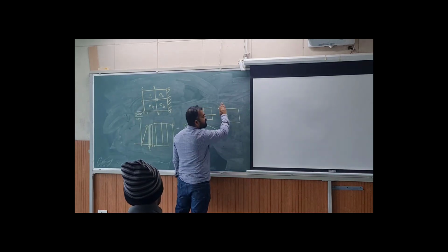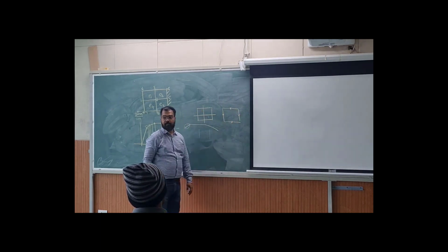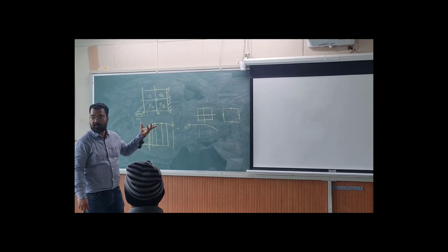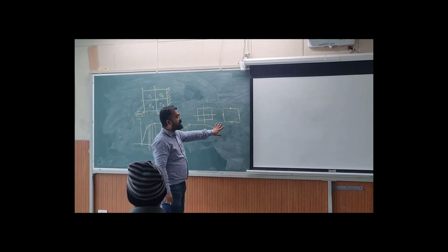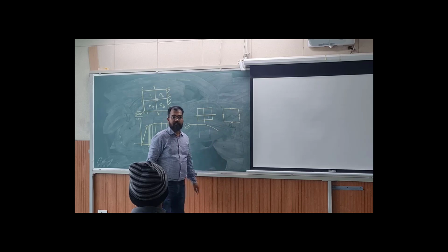So I make it a quadratic shape function, which will mean that there are mid nodes. So again you will have, well, a smaller number of degrees of freedom. A little bit less in comparison to that one. So here you have 9, here you have 8. So 2 values you have decreased. Good. Apart from that, what else can you do?